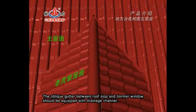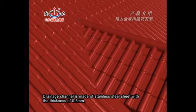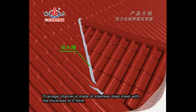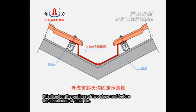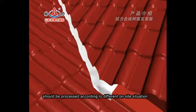The oblique gutter between roof slope and dormer window should be equipped with a drainage channel. The drainage channel is made of stainless steel sheet with a thickness of 0.5 mm. It is fixed on the purlins of the two-slope roof before the installation of main tile. The flushing panel between drainage channel and dormer window should be processed according to different on-site situations.